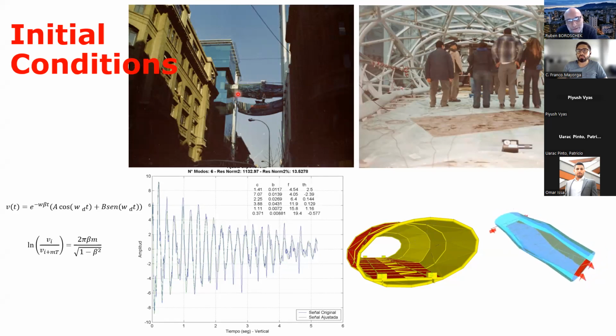So the first thing I did with my students in the dynamics class was to go onto the bridge during construction and allow them to jump on the bridge or walk on the bridge, with very high sensitivity sensors. This is, for example, to monitor the transfer of motion or the vertical. With that, we get a recording of the motion, and I teach them how to analyze these records so they can get the basic damping, frequency, or mode shape of the structure. Then we update a numerical model of the structure and try to simulate the relative vibration of these two buildings and design the shock absorbers.